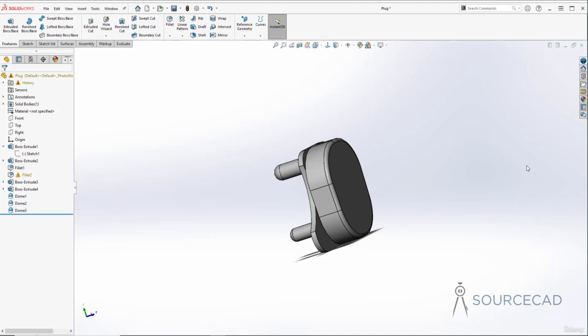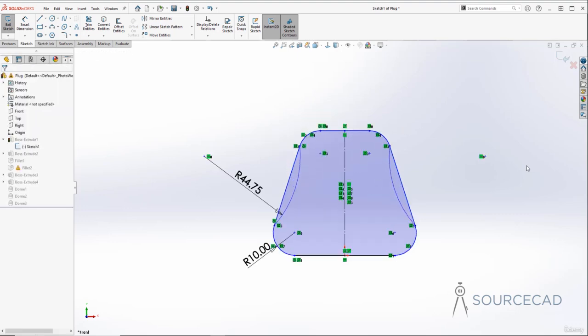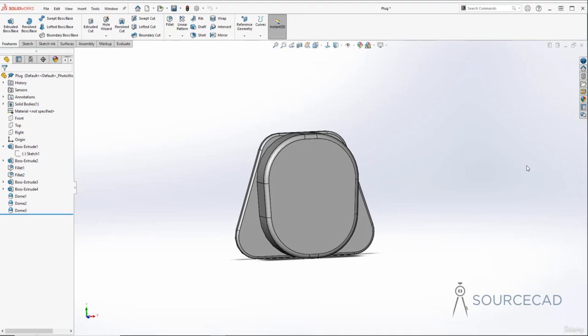In these kinds of situations, you can replace the sketch entity with the new one instead of simply deleting it, and that avoids any kind of error. So now I'll press Ctrl Z a couple of times so that we are back to the main drawing without any error. Again, Ctrl Z, and there we are. This is the original drawing, no error whatsoever.